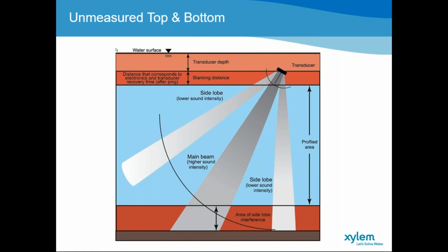I just want to highlight this. This is also applicable to all side-looking instruments and up-looking instruments, where we have a cutoff. The last 10% of the data collection we don't use at all for any flow measurements or calculations.